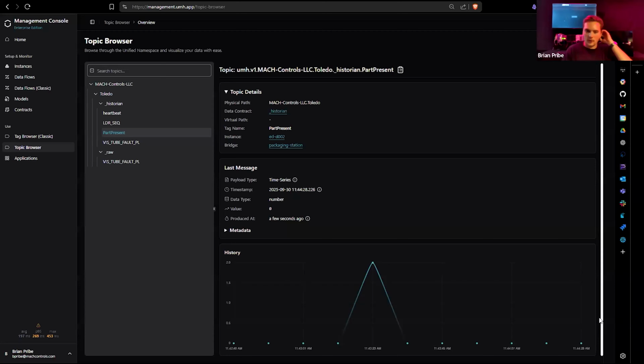And the best part about this is that you're able to get a lot of the raw values that come directly out of the machines. A lot of the tags that come off of the PLC are not the most organized. They're not the most thought out as to what the business is looking for and interpreting. The tags are built out just for that machine to operate, with not much else to think on. So when it comes to aggregating this data up and out, it's really difficult to even start doing basic mappings into UDTs and stuff like that.